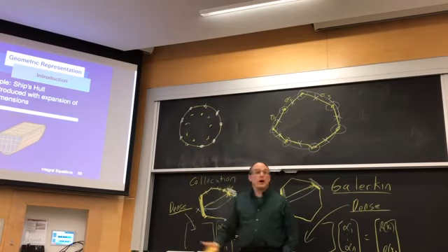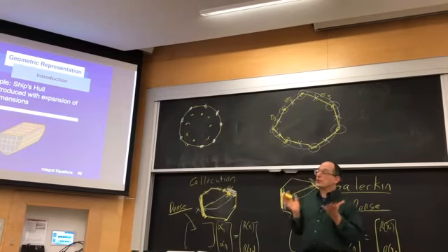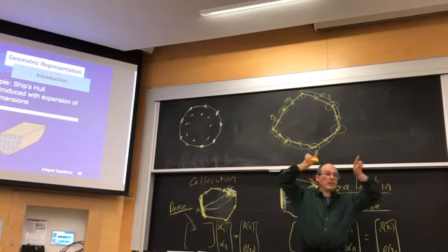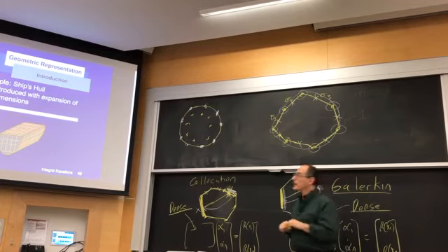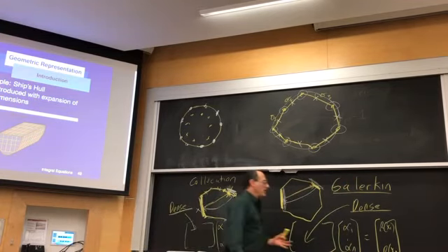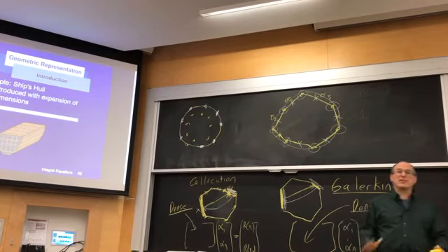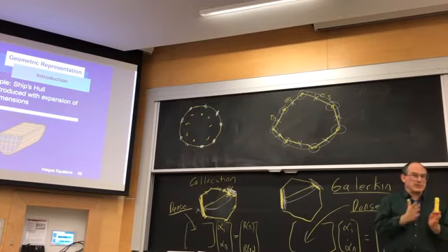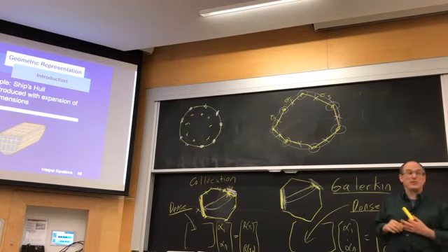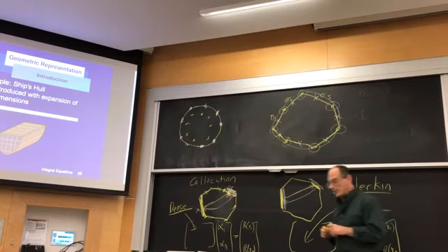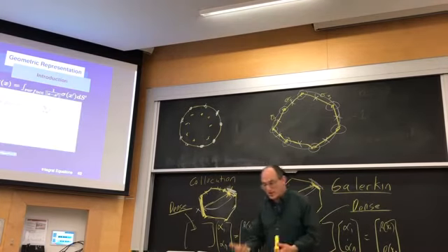So now you have a ship hull, and you're going to take the surface and represent it with something. If it's 2D and you have a curve, you can connect it up with straight lines. In 3D, you have to connect it up with panels, and if you try to keep all the points on the panels in the same plane, the panels don't actually connect up to each other. There is a term called leaky panels, because they used to use them for ship hulls, but they would have gaps between them.